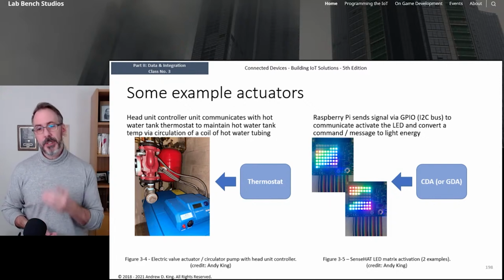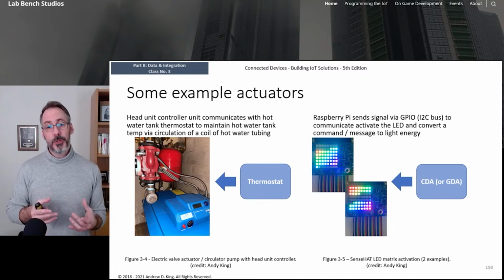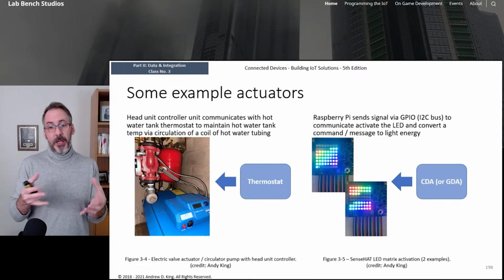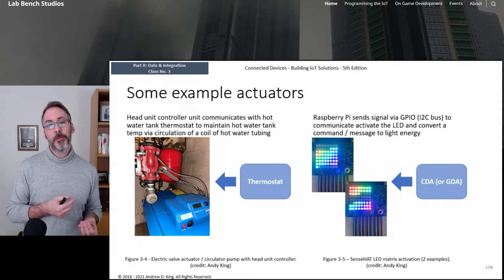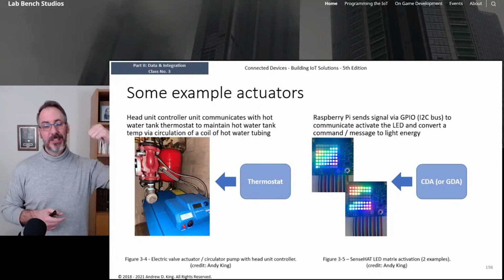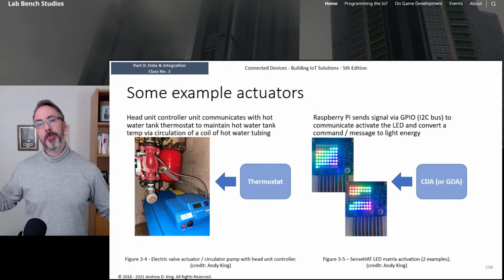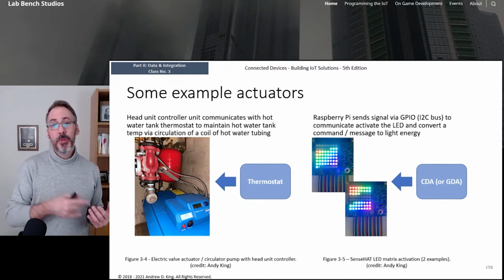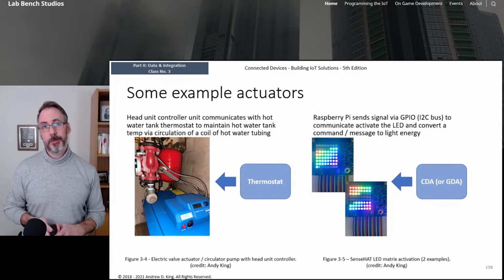And the purpose of this is to receive a signal from a thermostat, and then the controller unit, which you actually see as that blue kind of robot looking thing sitting at the bottom right hand side, will interpret the message coming from the thermostat and say, hey, you know what? I have to tell this circulator pump, the red thing in the upper left corner, to start spinning its impeller to move the water that the big blue thing at the bottom is heating up through the heating system, or in this particular case, through one particular zone.